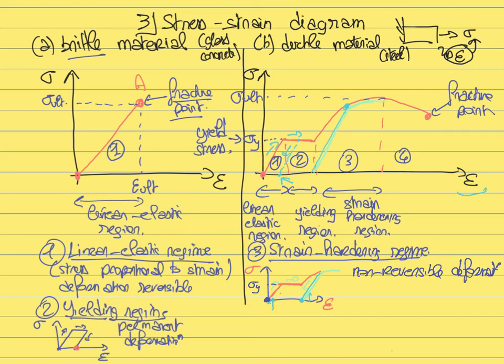Now the question is, after you have loaded and then unloaded, the material remains permanently deformed. Now when you reload this material, initially its stress will increase linearly with the strain again. So you will have now a linear elastic domain up to a given point where again the material will start to show some plastic deformation, where if you were to unload it after this, again it would be permanently deformed.